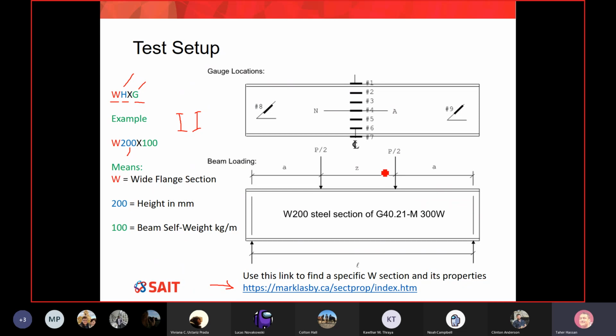Now, before we leave this slide, there are a few things I want everyone to see. On the beam, we fix something called strain gauges. Look at the name, strain gauge. Those strain gauges are small elements that we can glue and stick to our beam, and what they do is measure the strain. A few observations from this slide: how many strain gauges did we fix on our beam? You can see the number. We have a total of 9 strain gauges.